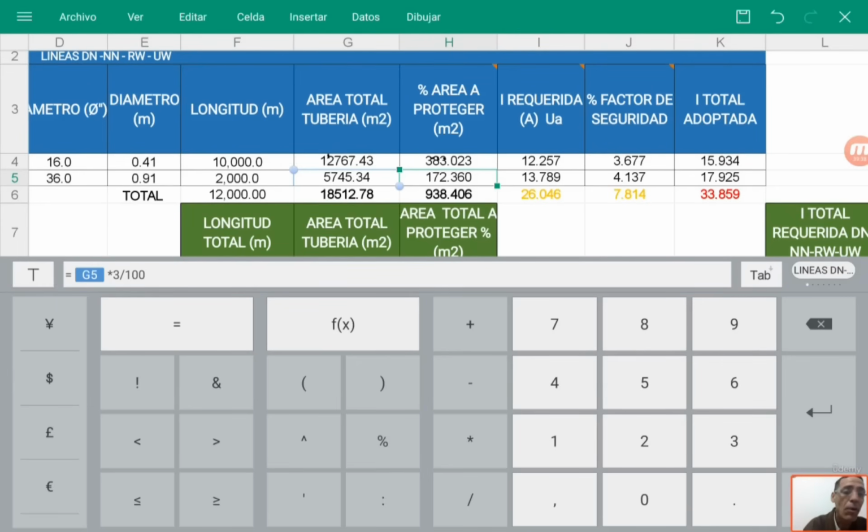But now let's move on. That's with the exposed area. That value is either given to us by the client, or we should go out to the field with a portable plant, a portable car battery, inject current into the pipeline, measure the potentials, calculate the current the pipes are consuming, and use that actual current density.